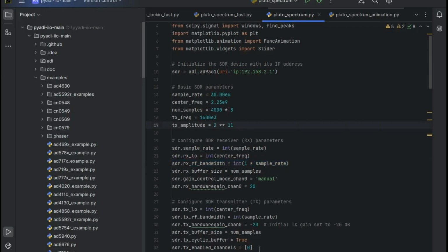One more thing, which I will talk about more in future videos, is that by default, ADALM Pluto comes with only one TX and one RX channel enabled. But you can modify the firmware of the IC inside ADALM Pluto and unlock the second channel. Not only that, you can unlock the frequency range of the LO.